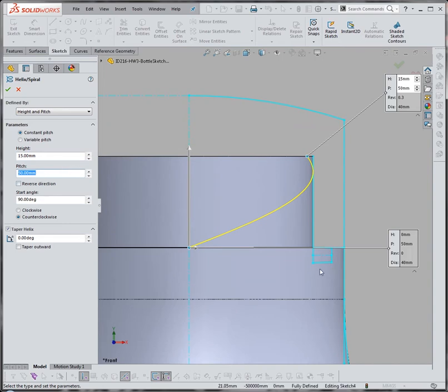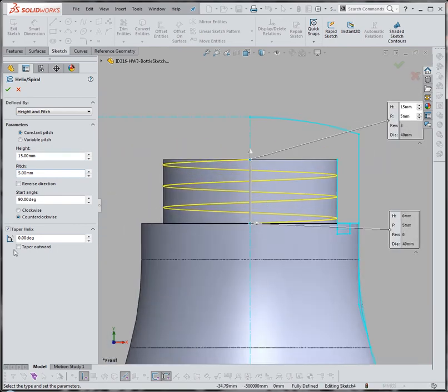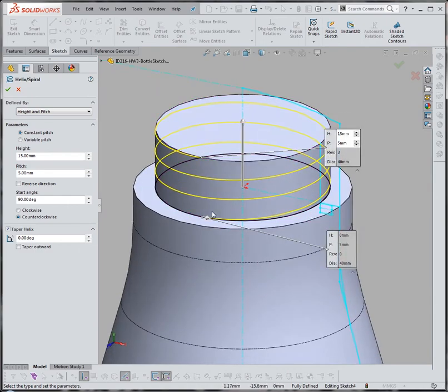And the pitch, I'm going to double the height of the thread. So right now my thread is 2.5 millimeters high. We entered that manually. I'll make the pitch 5 millimeters. And that will give me room for a positive thread, and then a space, and then a positive thread again, and a space, so that our threads are spaced evenly. And I'm just going to make sure that my threads are checked onto counterclockwise, because it's America, and we unscrew to the left.